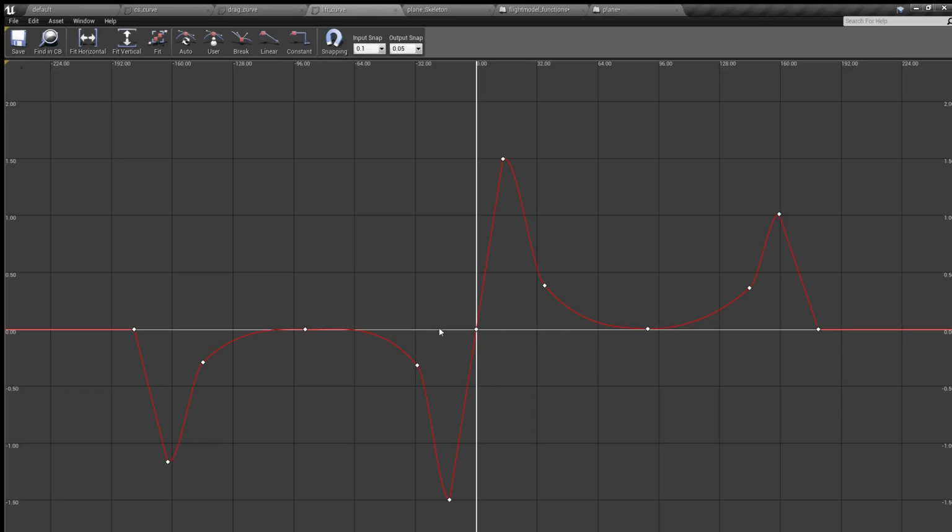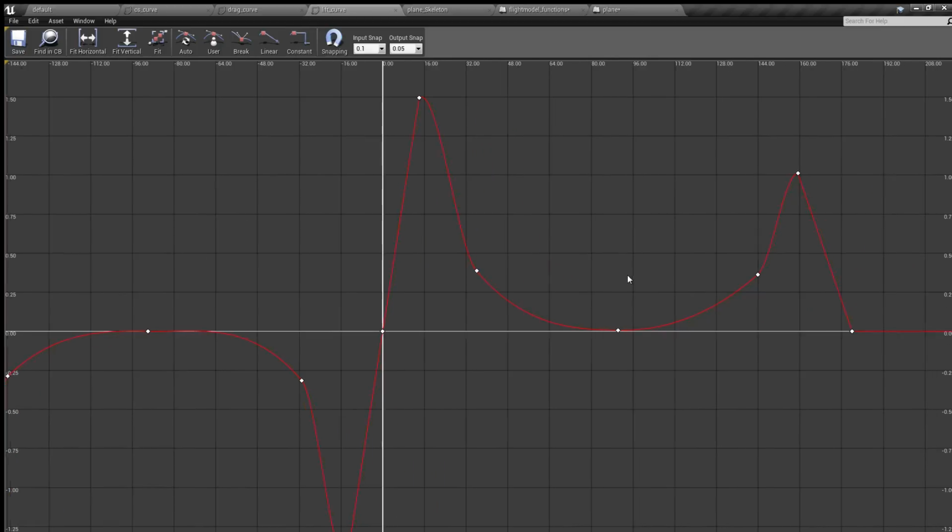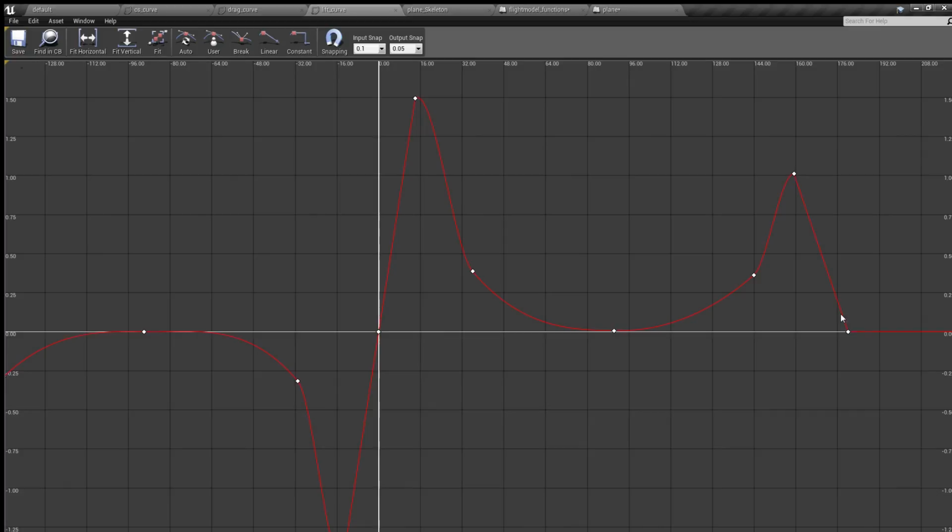if the airplane is flying straight at zero angle of attack, the lift is zero. If you pull up, the lift will increase until you reach the point at which it stalls. Then you have some residual lift. If you're falling straight down, lift is zero, and there's a bit of lift if the airplane is flying backwards, but of course the airfoil is not effective that way, so lift is diminished.